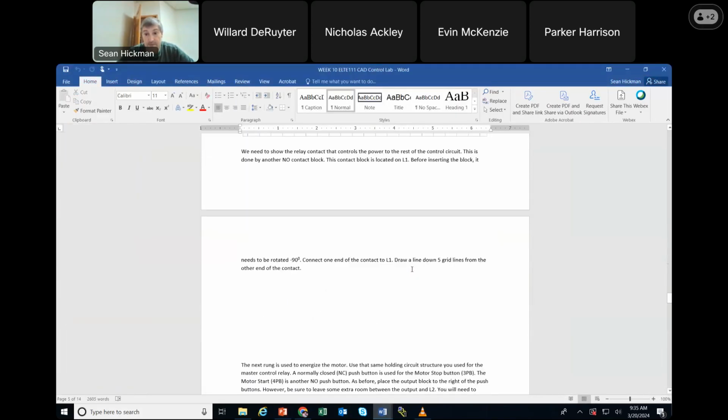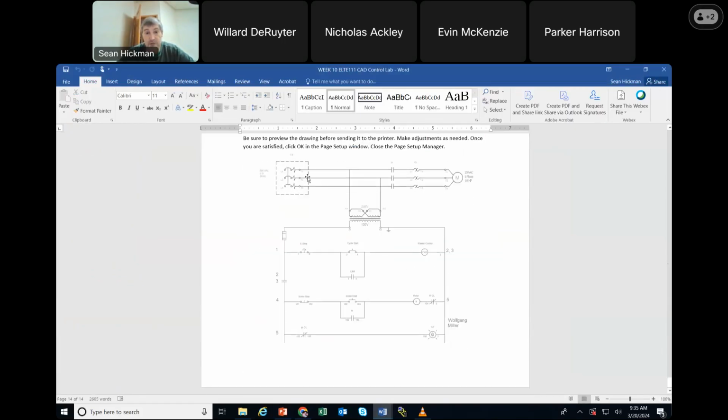Let's go to the bottom of this page. I think that's what you're showing. Power circuit up here. It says stop, it says start. So when I hit start, this control relay comes on. Here's the memory. So hit start here, and this stays on. This is on, which closes this, this, and this. And then boom, a 3-phase motor comes on. If I hit stop, boom, this goes off, which opens the memory and opens the 1, 2, 3 power.